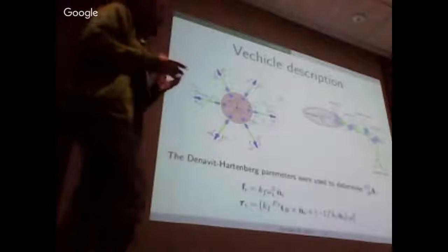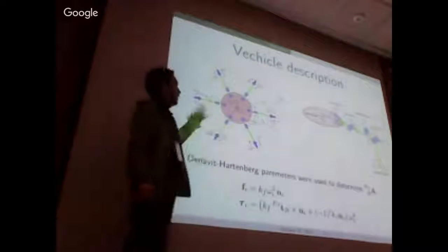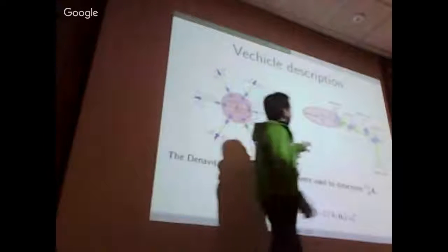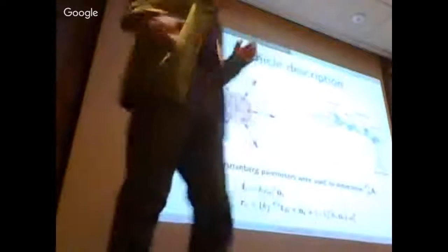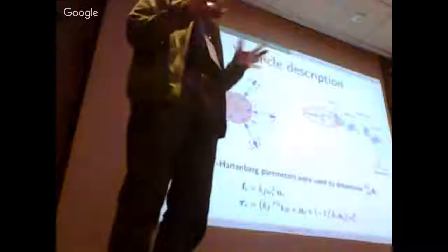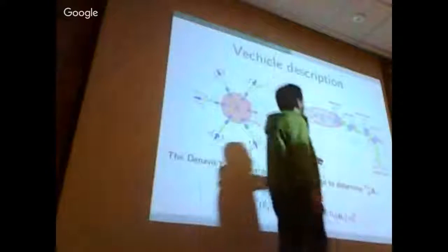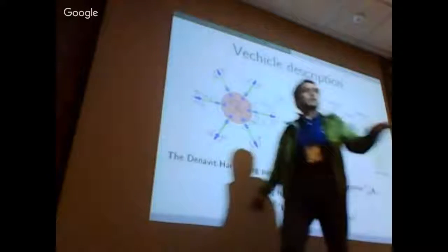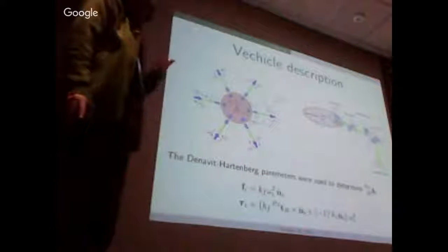The one we followed is we model the vehicle as a normal hexapod, but this time each link has 3 degrees of freedom. It has what we call a swing axis, a lift axis, and a knee axis. So each link has 3 degrees of freedom, and as you can see, the thrust motor, the brushless motor, is mounted over the femur of the link. So it is possible to change the orientation of the thrust force with respect to the center of mass of the vehicle.